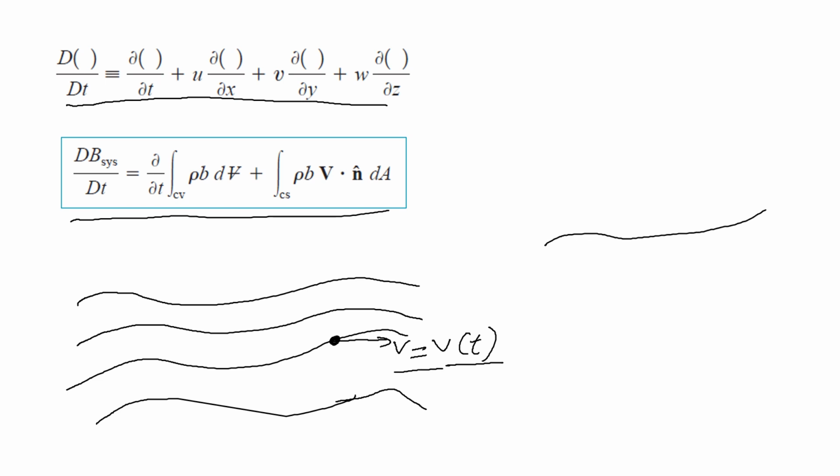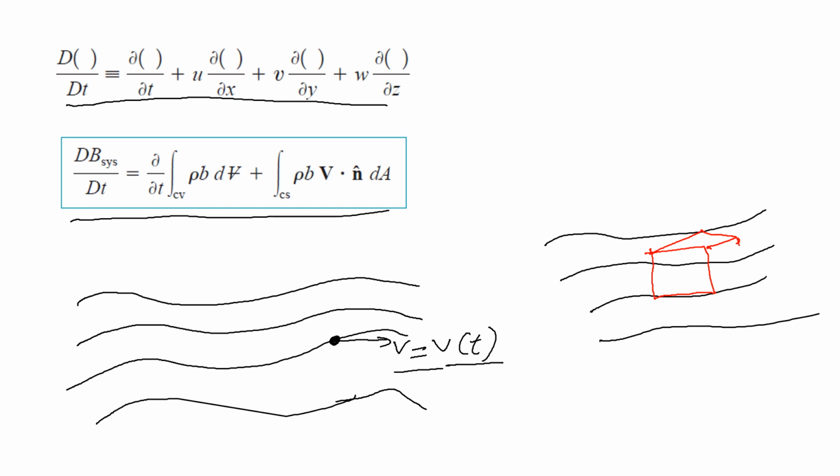But in the Eulerian flow description, what we do is we define a control volume. Whatever flow is passing through that volume, that is what our study is about, those particles that are flowing into the volume. So when we write something like this, we will write it both as a function of position and time. The properties in Eulerian system will be represented both as a function of position and time, and in Lagrangian system it will be represented as a function of time only.